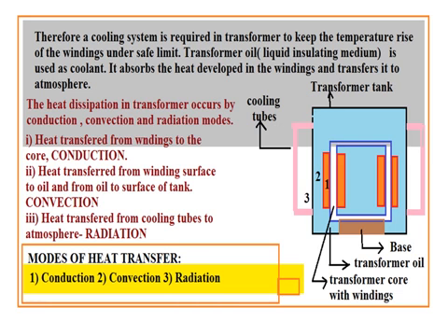Hence, we have to see that temperature rise in the winding should be maintained under safe limit. If it increases linearly, then there is a problem to insulation provided for the windings. Hence, a cooling system is necessary to control the temperature rise of the windings within certain limits. This shows why the cooling is necessary.